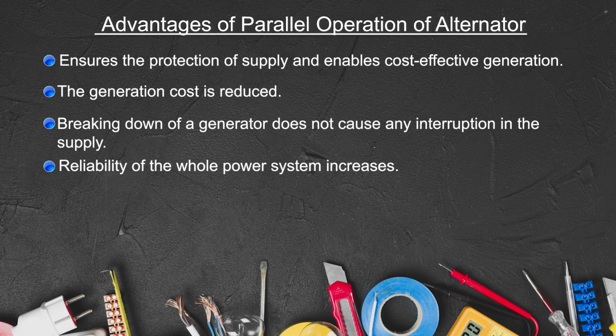We all know what we mean by reliability. Reliability is the continuous supply of the power to the consumers. So the reliability of multiple machines connected in parallel is always better than a single, larger machine.